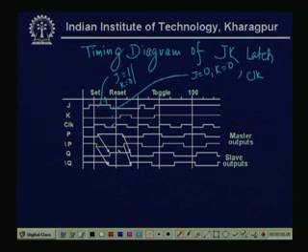See here that Q becomes 1, that means this is a reset Q and this is Q complement. That means the output of the first latch, P, comes here, and the other output of the previous latch comes here.